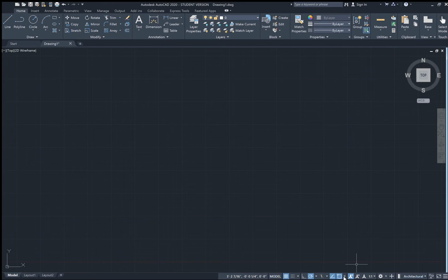This here is called Object Snap. The way Object Snap works is, if you draw a line and you want to connect that line and draw another line, these preferences allow your cursor to easily snap onto the end of one line and tell the computer to draw another line from it. As you can see here, if I were to disable endpoint and draw just some random line, if we were to try to draw another line here, it wouldn't quite be able to snap onto the end.